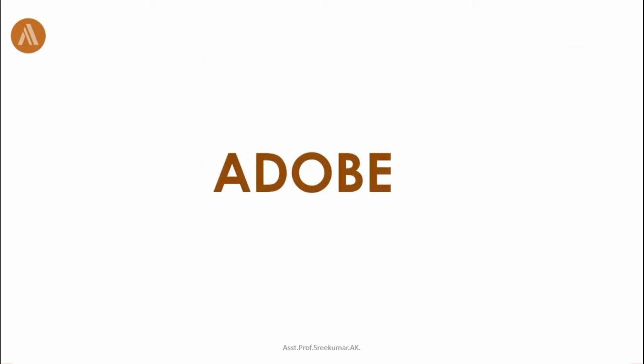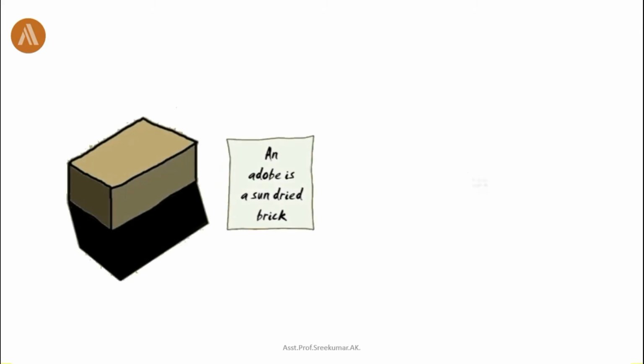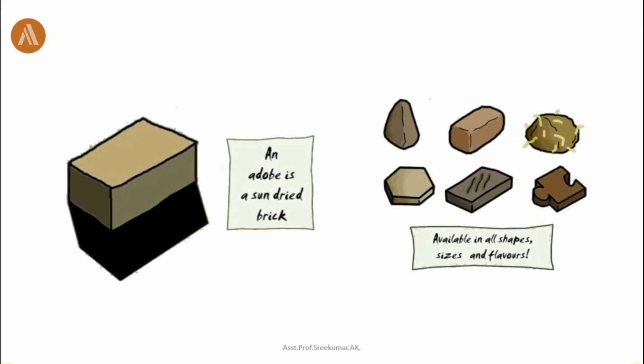Now let's move on to the next system of mud construction. It's the Adobe. It's known all over the world as Adobe. Here in India, we know it as sun-dried bricks. This is probably the most popular form of mud walling because the mud blocks or bricks can be made by anyone, and after drying they can be stored until there are enough of them and the right time to build has come.